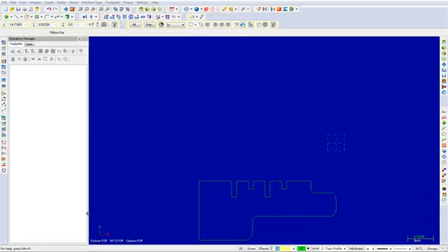The fifth tool is a boring bar with a diameter minimum of 1 inch and an insert with an angle of 75 degrees. The sixth tool is an ID groove with a minimum of 1 inch diameter at an insert of 75 degrees. This tool will be used to cut the grooves on the inside of the part. Finally, the last tool that we will use is an OD thread left large tool.